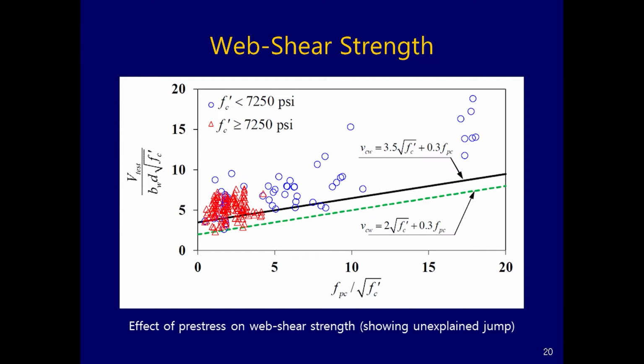That way, for beams with relatively small pre-compression, shear capacity is more reasonably fitted. So 3.5 may not be appropriate, even though it was a conservative derivation in the original literature.